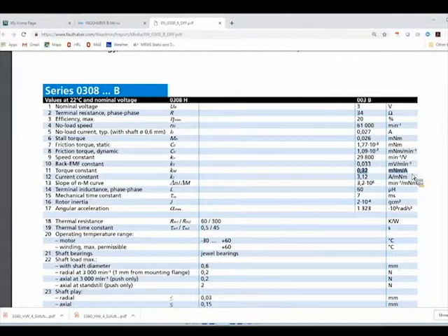This would be a very common thing you would see in a spec sheet. It basically gives you an idea how strong this motor is for a unit of current that goes through it. Like I said, this one's weak. Some of the bigger motors get on the order of around 1 newton meter per amp, for something that you could actually carry around. And then, of course, industrial motors would need a hoist to lift. Then you're talking about many, many newton meters per amp for the system, and also the ability to put a lot of current into the system, really high current into those motors.